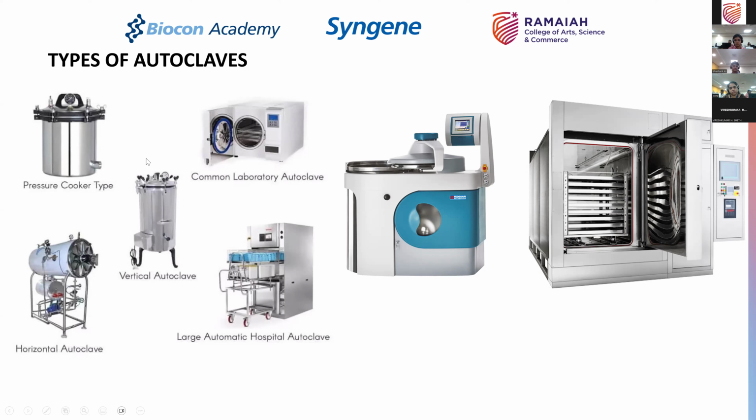Then there are vertical autoclaves. These are normally in the range of up to 10 liters, because they are portable. You can keep them on a laboratory bench and operate them. Then you have larger vertical autoclaves in the range of about 40, 100, 200, or 300 liters. They are very similar to the pressure cooker design, but in this case there is an inner chamber and an outer chamber. The outer chamber is where the water gets filled up. The inner chamber is where you keep the loads, and then you again heat it electrically.